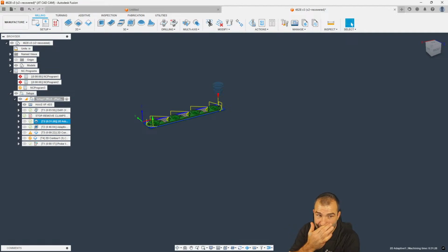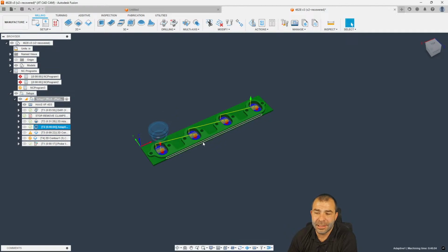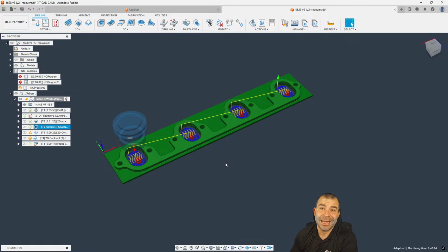So it looks like we have another question. Yeah, so unless you're on, and I may be wrong on this, an educational license or something like at a high school, I know back in the day there were Chromebook versions. All of your stuff is actually calculated local. So I think a lot of people confuse the idea. It is not actually a cloud-based software. It uses the cloud. It's a hybrid. It's a desktop install that uses the cloud for data storage. So your toolpaths are all calculated locally, which means you are technically limited by your computer's performance more than anything.